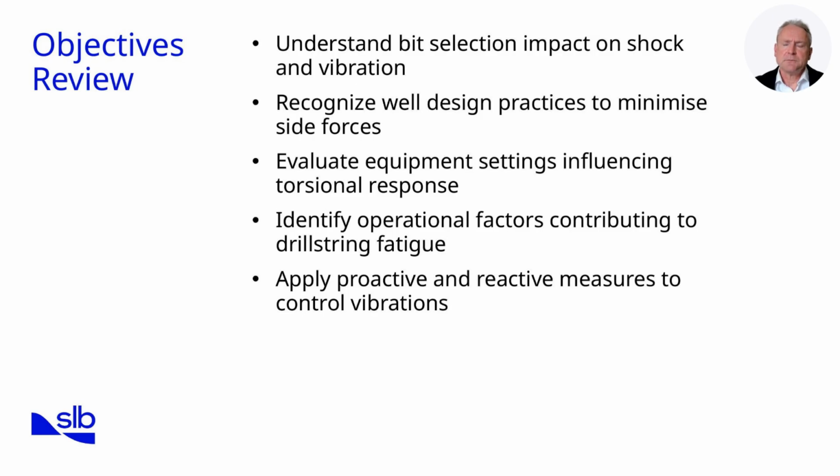Third, we evaluated equipment settings that shape torsional response. We looked at RPM, torque limiters, and modern soft torque systems that manage fluctuations in power delivery. Fourth, we identified operational factors contributing to drill string fatigue, from reaming and hole cleaning to poor stabilization and bit balling. Finally, we applied both proactive and reactive measures to vibration control, reinforcing the need for real-time parameter adjustment as well as engineered design. Together, these objectives provide a structured framework for managing shocks and vibrations across the drilling process. This brings us to the conclusion of the sub-module.